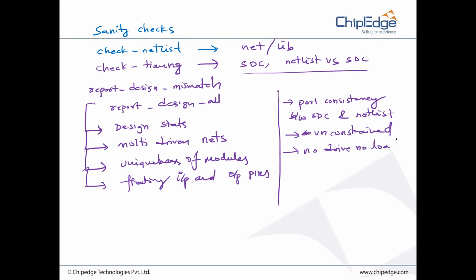Yes or no, guys? False paths. Okay, false paths. In this design, you have seen only false paths, but in some other designs, you may get these things also. Or you may get clock not found, or there are some combinational loops like this. So many errors you can be getting from this.